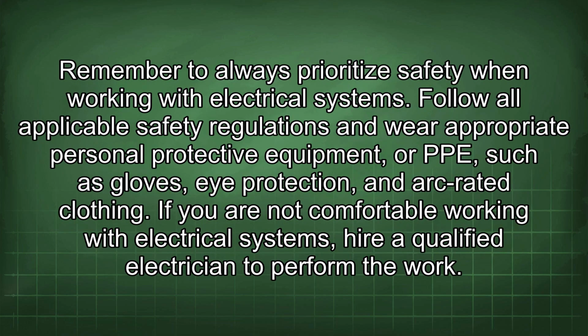Remember to always prioritize safety when working with electrical systems. Follow all applicable safety regulations and wear appropriate personal protective equipment, or PPE, such as gloves, eye protection, and arc-rated clothing. If you are not comfortable working with electrical systems, hire a qualified electrician to perform the work.